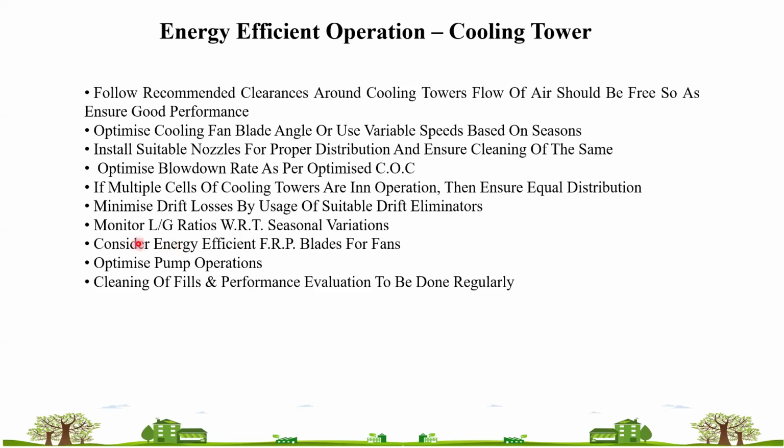Then install suitable size of nozzles for the proper distribution and ensure cleaning of the same. Means nozzle cleaning, nozzle spraying has to be very critical in the cooling tower. Then optimize blowdown rate as per optimized COC. Means your blowdown has to be critical but not frequent. So as per your cycle of concentration, the required blowdown has to be given to the cooling tower.